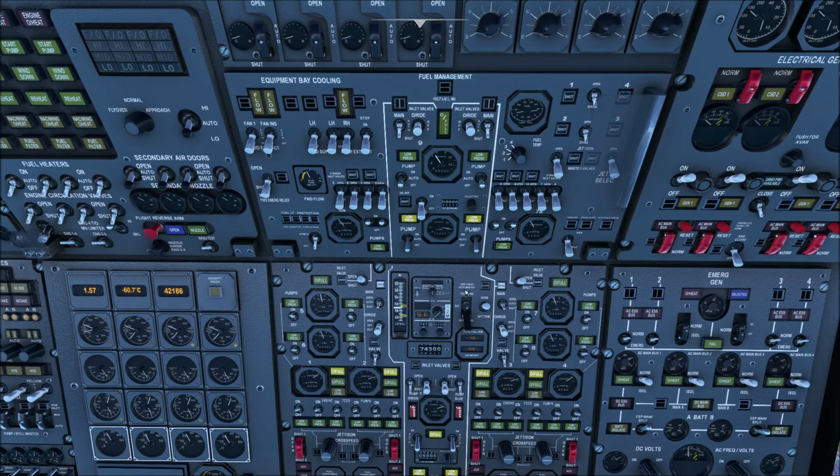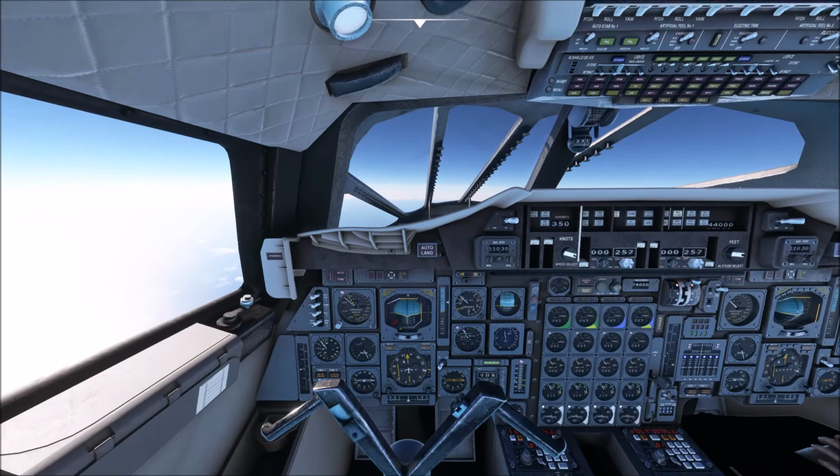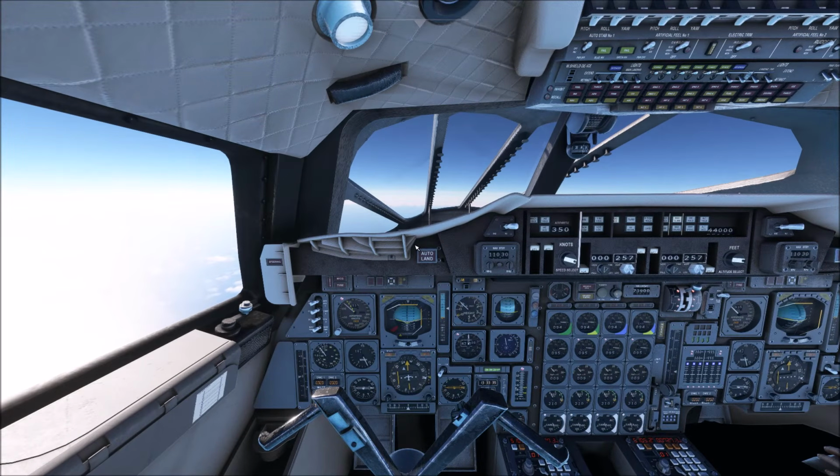Just monitoring that now. It'll be slower. Yeah, 56.7, so that's climbing now. We're sending fuel from here to these tanks. So it's not as far back, so it's not moving as quickly. But it's emptying fuel out of that front tank to keep this moving. So it's an extra function, and it'll keep filling these up. Remember to come back to that in a minute. Once you've got 59, of course, you're done then, so you can leave it. Okay, Mach 1.6 just gone, wobbling about there, probably because of the air outside.